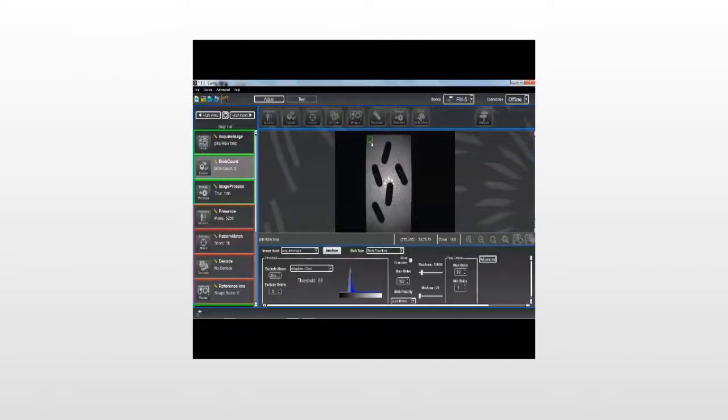Well, just like with the other plugins, I get my region of interest. I'm going to set that up around the area in the image where the objects are that I want to recognize. Well, you see right away I get all this little noise pops up where the algorithm is detecting just slight illumination variations in the image. I can change some of that. I'm going to go to an adaptive background threshold where now the threshold used sort of adapts across the image for those lighting variations. I still get a couple of them in here, as you can see.